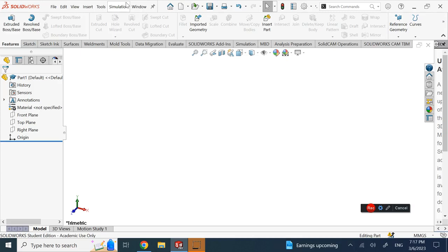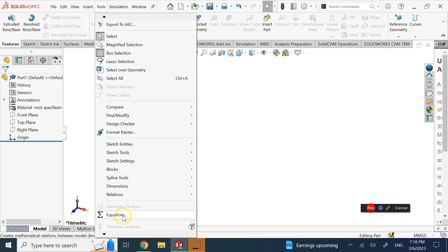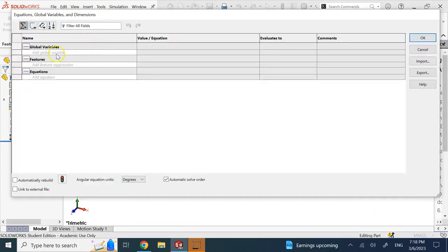If you go to that single place and change that value, then all of those CAD files are affected by it. We know that in each CAD file, we can go to Tools, add equations, and define global variables, but these global variables for one file are not shared with another file. So the idea is, how do we share the same parameter, the same variable, among several separate CAD files?